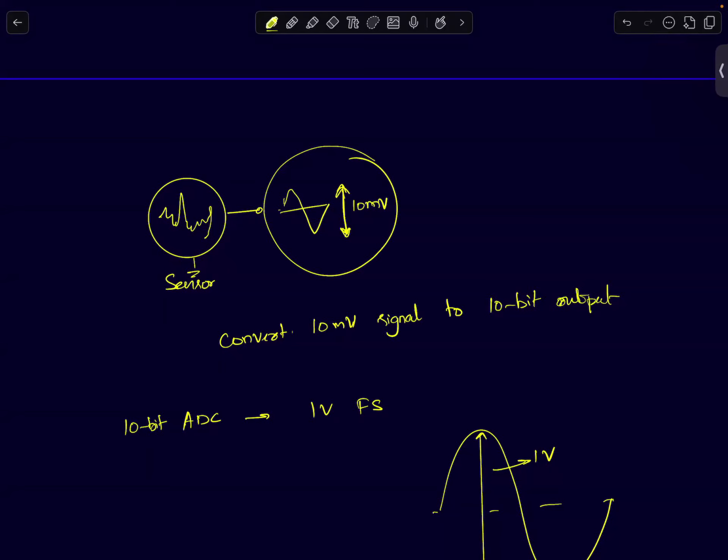Okay, so guys, this is not history now. I want you to come back to the problem solving mode now. We are looking at the mathematics here. So your guy has to design. It's given that the sensor produces an output whose peak to peak is 10 millivolts and average is 0. Which means you can think that the output of the sensor is a sinusoid which goes 5 millivolts above 0 volts and 5 millivolts below 0 volts. This is the output it produces.